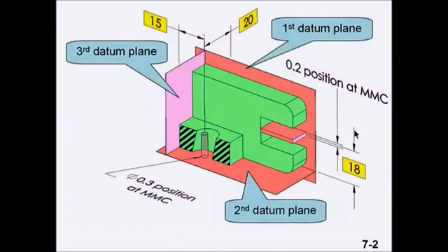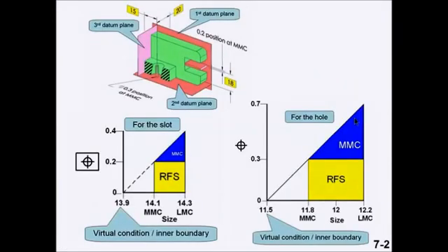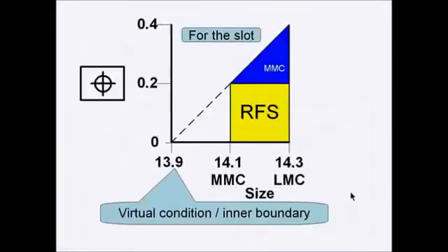One way, the traditional way, is to think about the tolerance zone controlling the axis or center plane of the feature. Discuss the calculation of virtual condition for each of the features. Use the dynamic tolerancing diagrams that were introduced in previous chapters to help with this. Point out that the virtual condition is a boundary that may not be violated. Because of this, it is often possible to evaluate position when the tolerance is modified at MMC by using a hard gauge, which assures that the virtual condition is not violated.